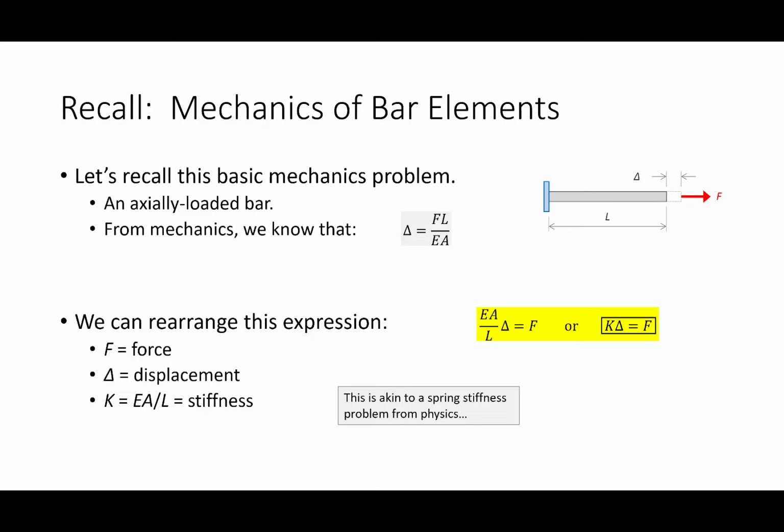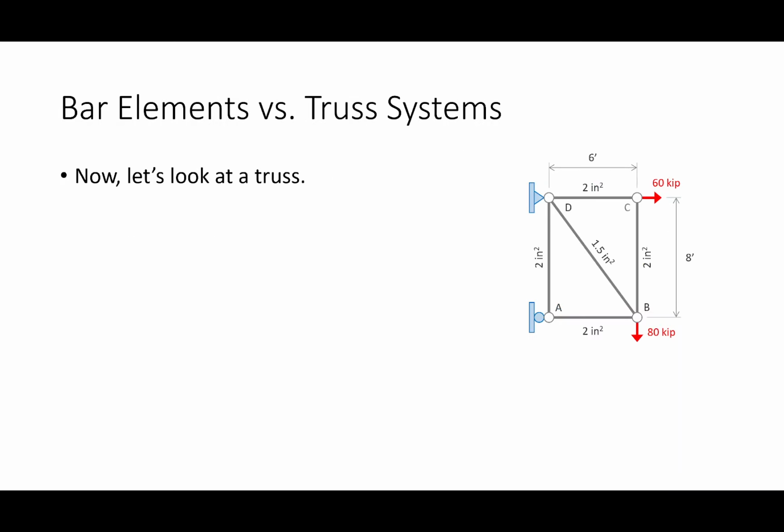Okay, all right, so my point is that if you look at a truss, a truss is just a bunch of bars. The idea is that we have fully formulated and fully solved a single bar element, while a truss is just an assemblage of bars. And I'm using this term assemblage very carefully. You're going to see why in a bit, because when we perform matrix analysis, one of the things we're going to need to do is assemble a stiffness matrix, okay?